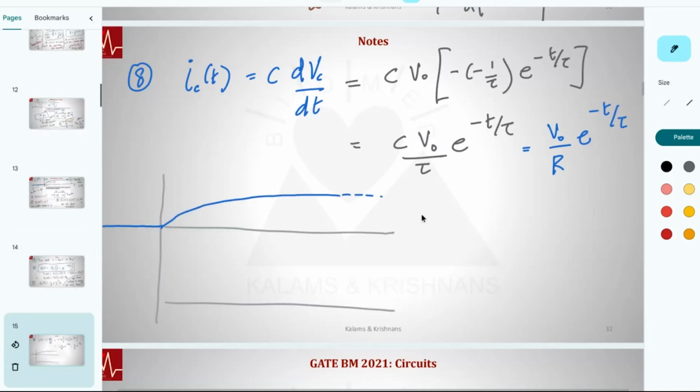What it says is that, this value is V naught, and that function is Vc of t. You take the derivative of this function, you get Ic of t. Here it is 0. I am only taking the part that is at time greater than 0, but there is a good mathematical way to deal with that. You have Dirac and Heaviside functions, but without complicating too much, the slope is discontinuous here. This is essentially finding the slope. Because of that, there is a jump, a sudden change in the slope. There is this initial value, and then it starts to decay exponentially.